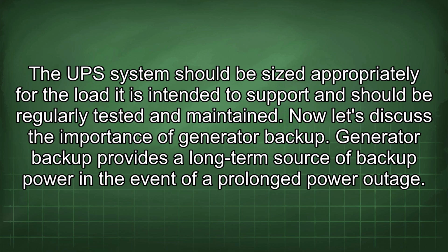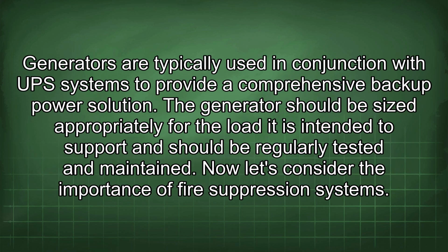Now let's discuss the importance of generator backup. Generator backup provides a long-term source of backup power in the event of a prolonged power outage. Generators are typically used in conjunction with UPS systems to provide a comprehensive backup power solution. The generator should be sized appropriately for the load it is intended to support and should be regularly tested and maintained.